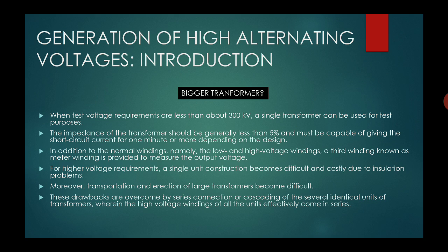The impedance of the transformer will also increase; generally it is 5% of the rating of the transformer. Moreover, the transportation and erection of these large transformers are very difficult. So there are certain difficulties in creating a single huge transformer.